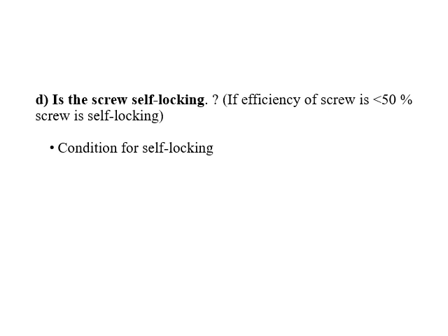Coming to whether the screw is self-locking, that is the fourth one we need to find out. There are two ways in which we can check self-locking. One is, if the efficiency is less than 50%, usually the screw is self-locking, or else we use equations to find it out. So we know the condition for self-locking, that is tan alpha should be less than f D2 plus fc Dc divided by D2 minus f into fc Dc. This is the equation to be used for this problem.